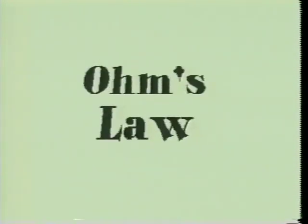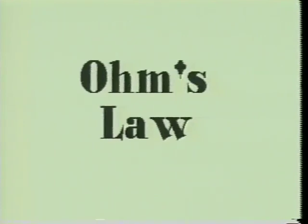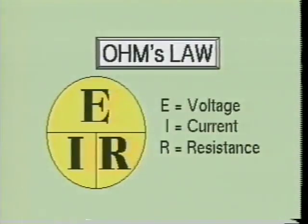This relationship was a most important discovery in electricity, and it was named Ohm's Law in his honor. The equation for Ohm's law is E = I × R. E represents the voltage, I represents the current, and R represents the resistance. We shall see that by knowing any two of these three variables, the third can be calculated very easily.